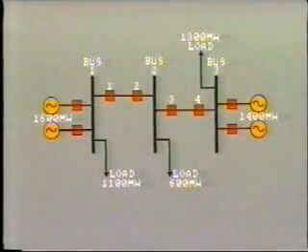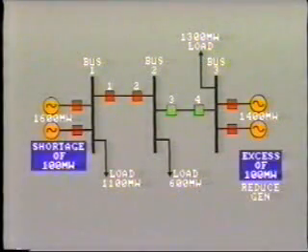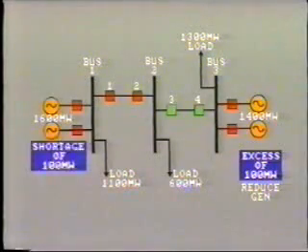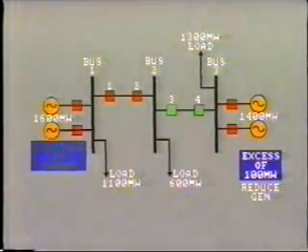So we have learned that where out-of-step conditions do exist, the systems must be separated. That each separate system or island will have to be stabilized before the two can be synchronized and reconnected. However, when the systems split into islands, we may run into another problem. That is, one of the islands may have insufficient generating capacity to meet the power demand.